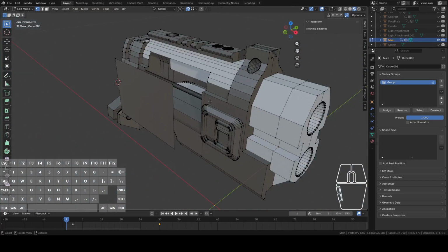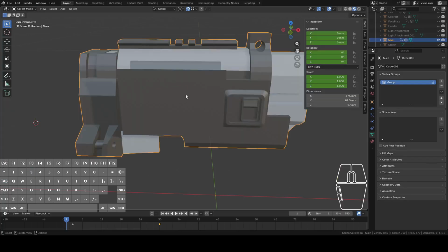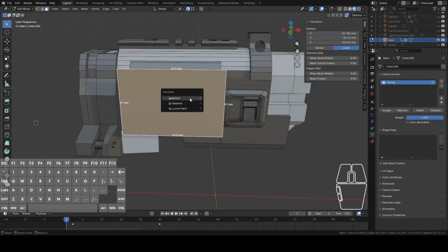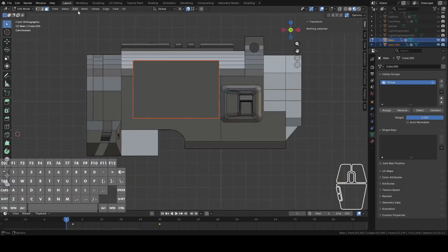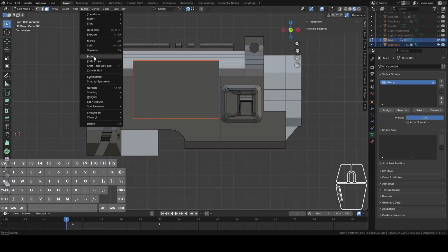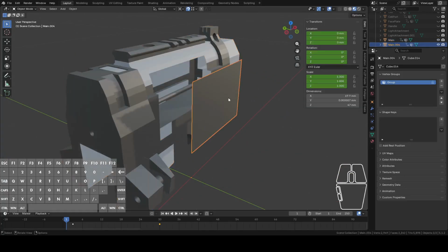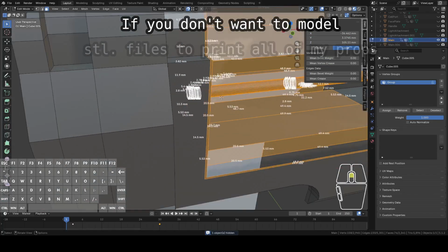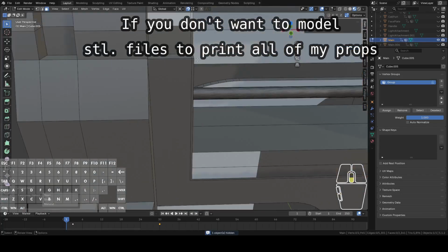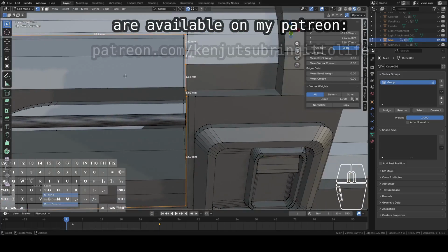Honestly, it doesn't matter. Select this one, P, separate selection. With that in edit mode, hit this orientation so it's dead on, knife project, cut through, and we can get rid of that with hide, and we should have that 0.5 square cut out here, which would do.